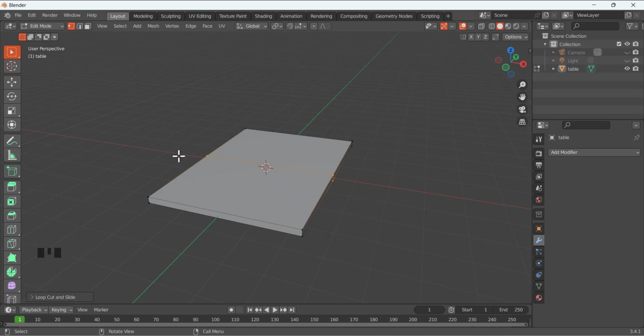Then again add a loop cut at this position. And if you are using the hotkeys, it will also give another control for this loop cut. So Control R to add another loop. I am adding a loop here. Now it's in the move condition. We don't want to move it; we want to place it in the same location. Add that. Okay, so it's added here. Again, I just undo it with Control Z.